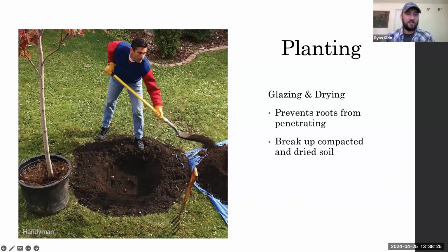One thing you might need to be concerned with, not so much in sandy soils, but maybe more in clay soils, is glazing and drying. So glazing is just caused by the shovel or digging equipment kind of hardening off or glazing over the hole. And then the drying is just from the hole being exposed for long periods of time. So real simple fix, just break that up before you fill in the planting hole. But that could be a potential barrier for roots penetrating the surrounding soil.